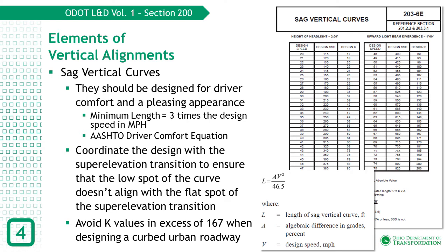Make sure to coordinate the sag vertical curve design with the superelevation transition design to ensure the low spot of the vertical curve does not align with the flat spot of the superelevation transition. Also, avoid excessively long sag vertical curves.